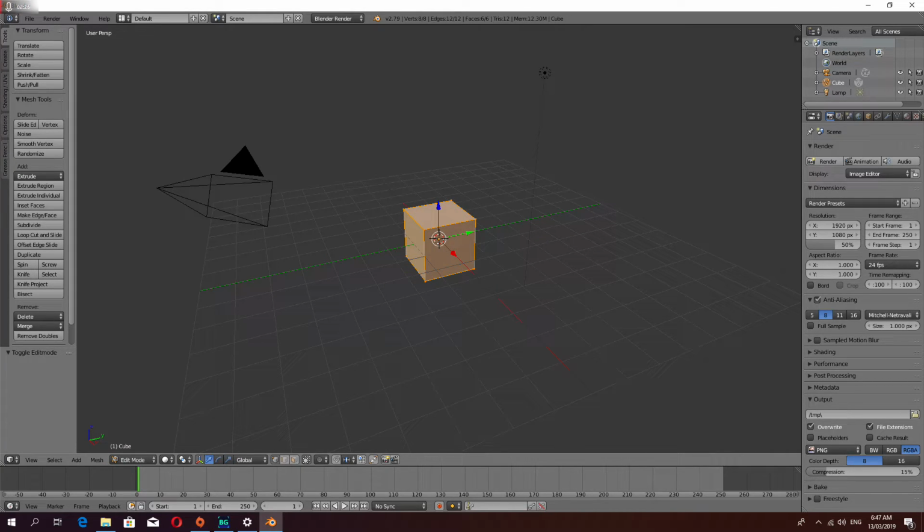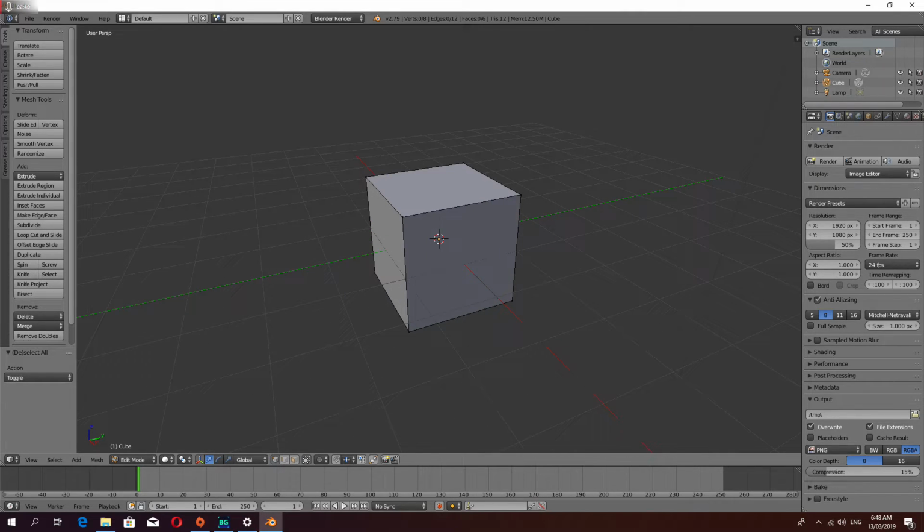Now notice in edit mode, some different things show up. We're just going to hit A to deselect everything, and this only selects everything in the object that we're editing. So see, it doesn't select everything in the scene now. We're in edit mode, we're editing that object. Now what this object has is some vertices, they're those little points there. It has some edges, they're the lines between the points, and it has some faces, that's the flat surfaces that connect the different points and edges.